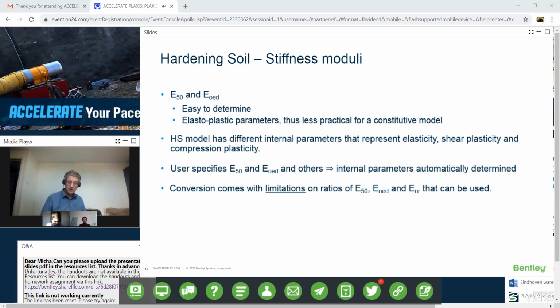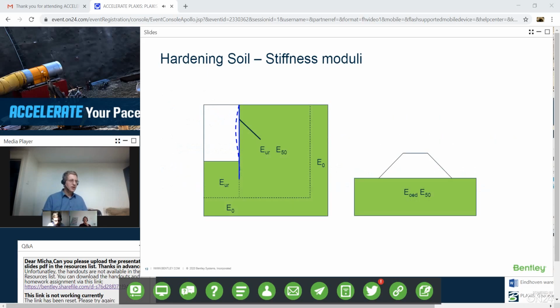You could use the soft soil model. If your soil is really that soft, it may actually also have creep behavior, so you have the soft soil creep model, for instance, that you could use. But the hardening soil model may be impossible to use if all three stiffnesses are equally important and you really have to have those values, and then hardening soil will tell you. So it's not that it will sneakily calculate with different values than you put in. If it has a problem because of the ratios, it will tell you, and if it tells you, you can act accordingly.